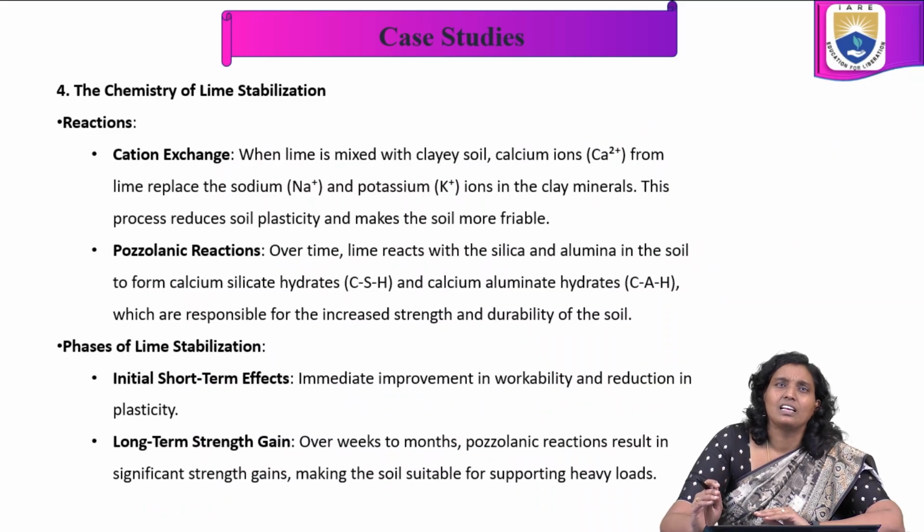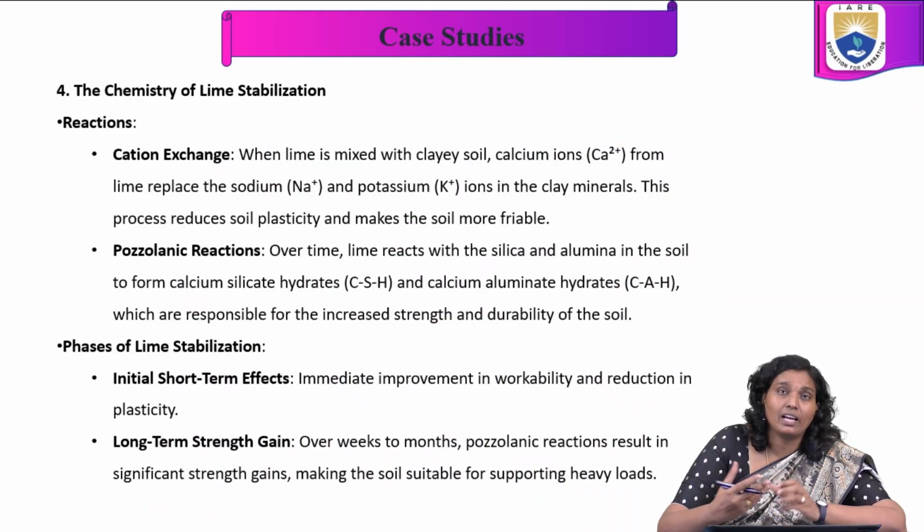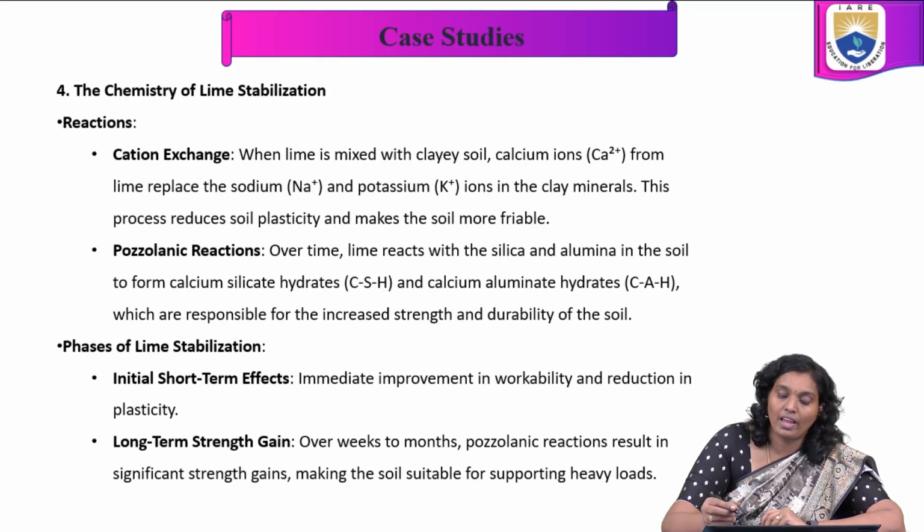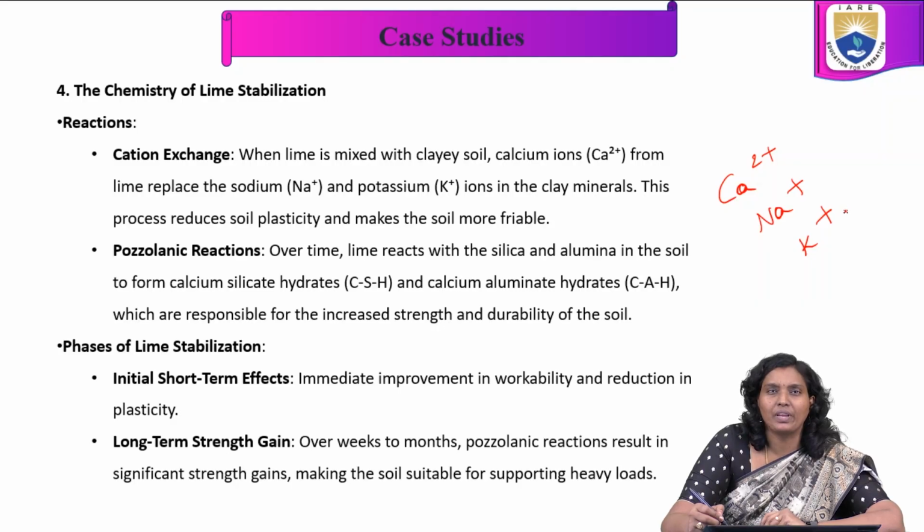What are the various reactions involved with lime? Cation exchange and pozzolanic reactions. When lime is mixed with clayey soil, the calcium ions, Ca2+, from lime replace the sodium, Na+, and potassium ions in the clay minerals.